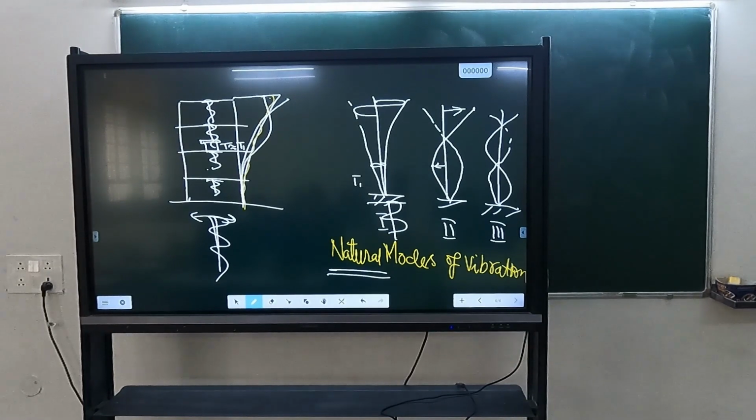All the energy will be transmitted corresponding to the harmonic of the fundamental period of the structure. A lot of energy will be focused there. So those secondary elements which have a period close to the fundamental period of the building will be subjected to very large damage, the same way as the 5 to 20-story buildings, whose period matches the period of the ground motion.